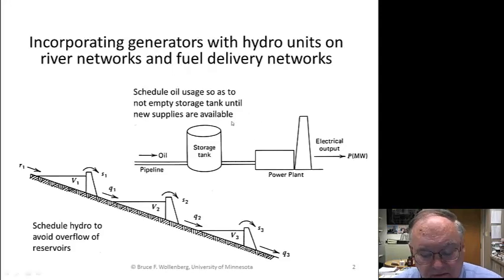so we go back to this same intro slide here, only this time we're talking again about water coming in to a reservoir. If you fill the reservoir too much, it spills. You have to provide for spill, because if you don't, the water is going to find some way to get around the dam. It's going to leak around, and what you don't want it to do is to get into the earth and rocks that are holding the sides of the dam and erode them away, and then basically can cause the dam to fail. So you want to have a controlled way.